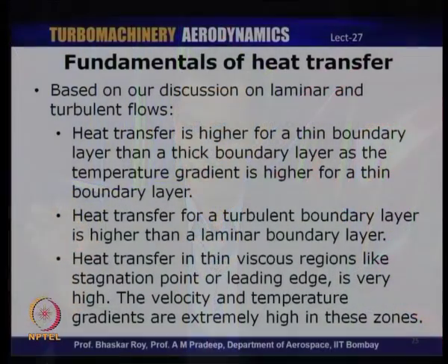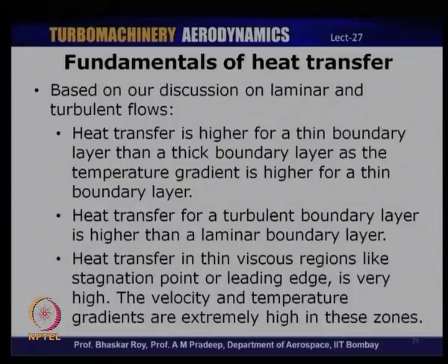So, let me just quickly recap the different points I have mentioned in the discussion on laminar and turbulent flows. We have seen that heat transfer is higher for a thin boundary layer than a thick boundary layer, as the temperature gradient obviously is higher for a thin boundary layer, and the buffer between the solid surface and the free stream is lower in a thinner boundary layer, and heat transfer in a turbulent boundary layer is higher than that of a laminar boundary layer.